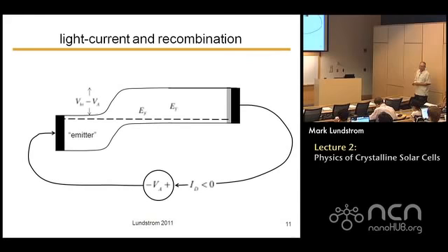But recombination can also occur under light. So if we're illuminating these, let's say we create 3 electron-hole pairs. All right. One of the electrons might diffuse to the p-n junction and get collected. That's what we want to happen. But some of them might diffuse, some of them might recombine through defects. Then I don't get any electron out the external circuit.